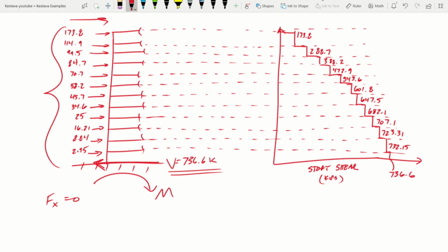So your base shear, that is your maximum shear, like you would in a cantilevered condition, which looks very eerily similar to that. And you know that your max, your Vu shear, and on top of that, your moment, are both at the base reaction. So that's what's going on here when you first want to think about that.